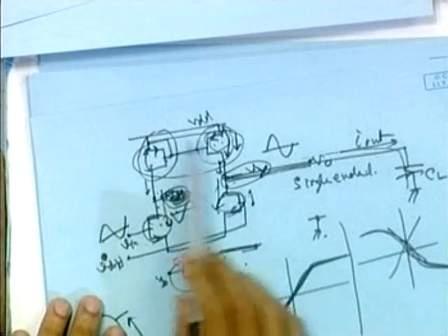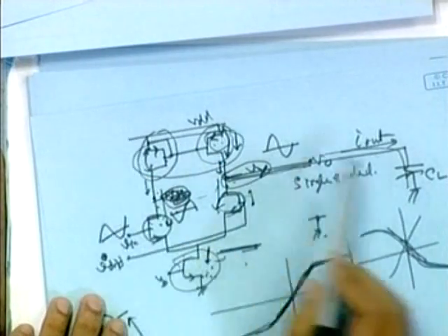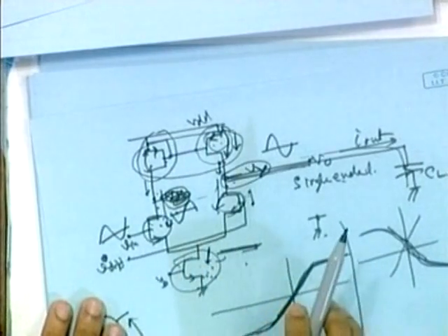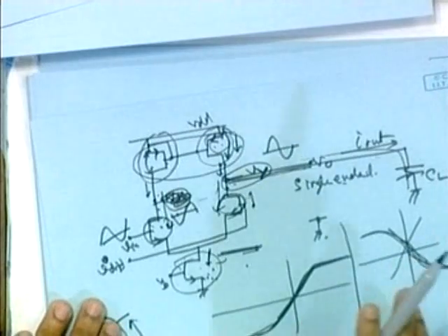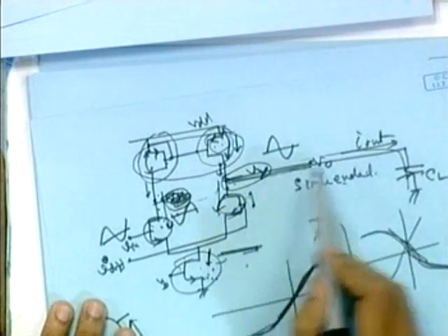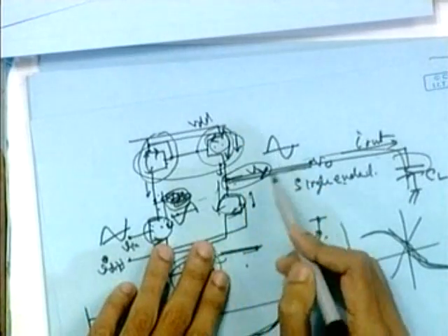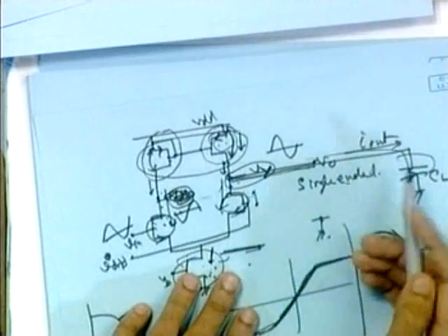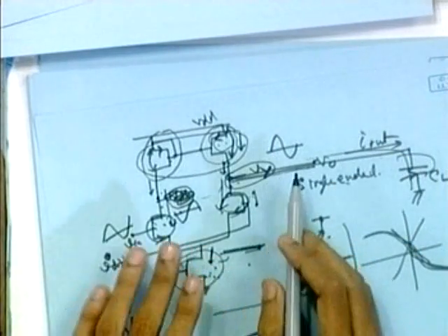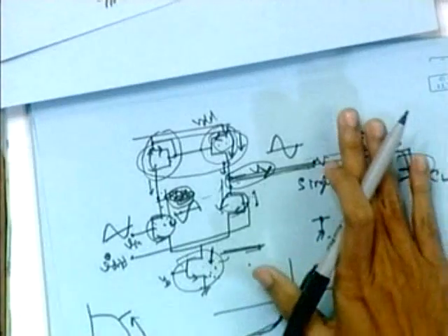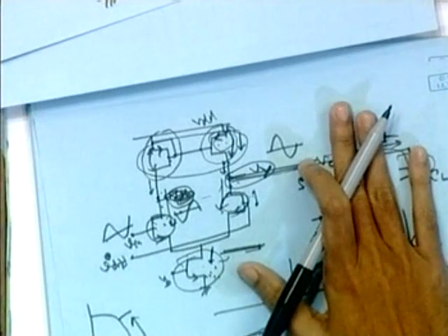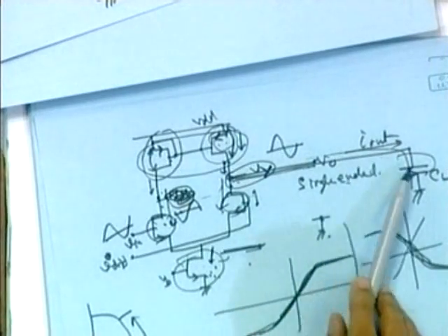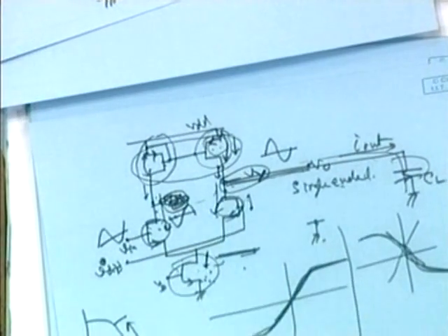So in this case all the transistors can be in saturation. If you connect a load here, that will balance this, and all the transistors can then operate in saturation. For all practical purposes we normally have a load, because this stage will have some other stage following it, and the input capacitance of that stage will act as a load. So though this is a textbook, unloaded kind of thing, you just explore and see what is happening, but for all practical uses we must have this load connected there.